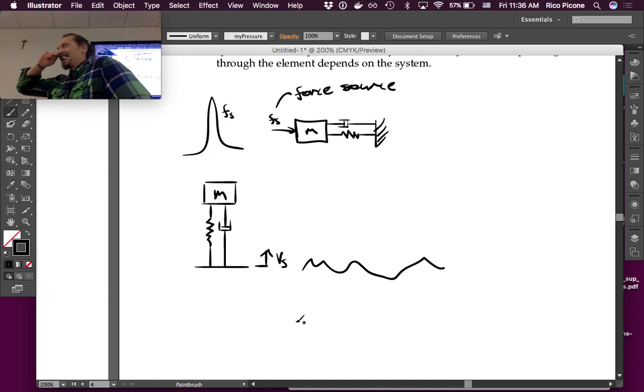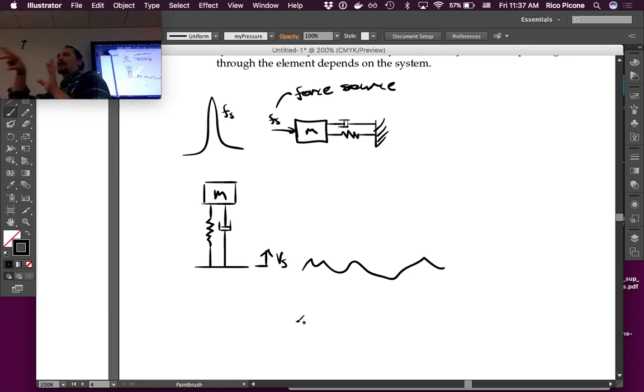So what they do is put these big masses on top of them, and they're tuned. Some of them are active, others can be just passive, so the mass might move around, but the building hopefully won't be moving around as much. You can take some of that energy and put it into the tuned mass spring damper system. It's pretty cool, and you can do a similar thing for vibrations coming through structures and minimizing them.